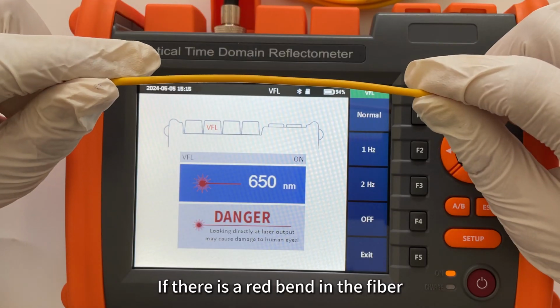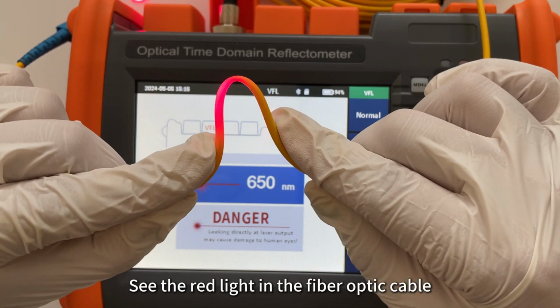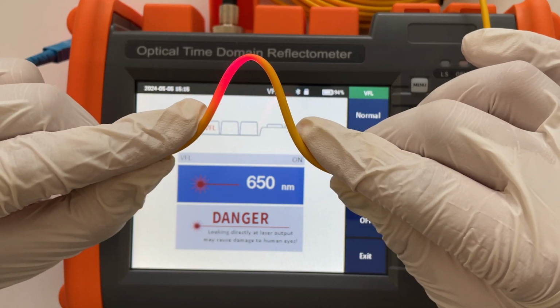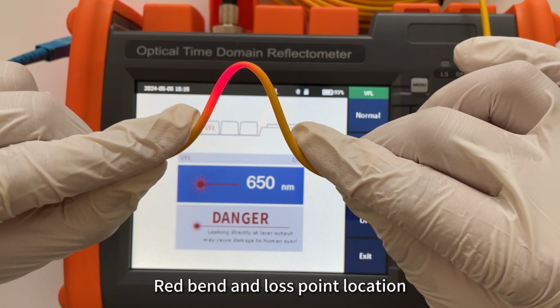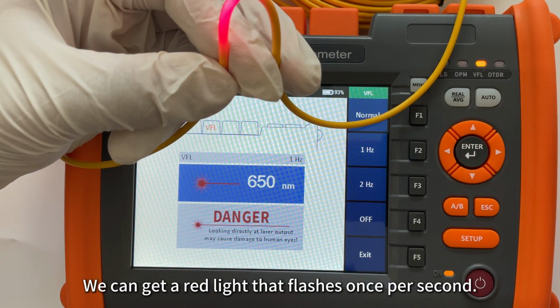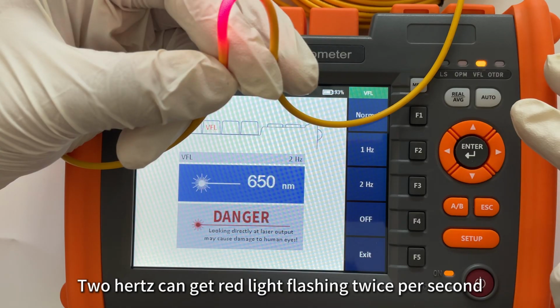If there is a red band in the fiber, or a loss point, it can be seen intuitively as red light leaking from the fiber optic cable, which determines the location of the red band and loss point. Click 1 Hz to get a red light that flashes once per second. 2 Hz gives red light flashing twice per second.